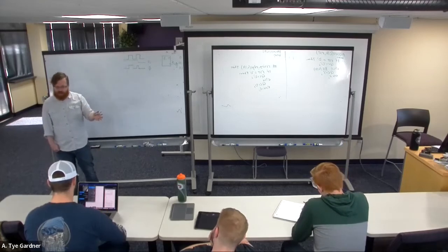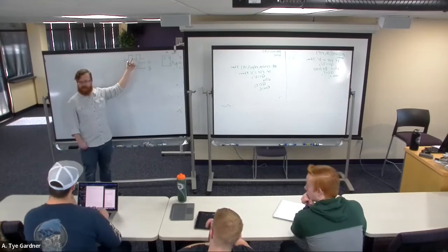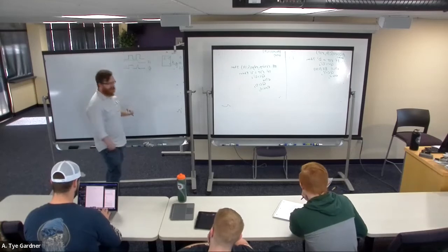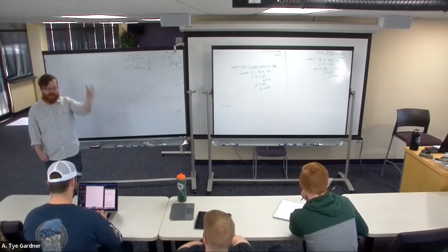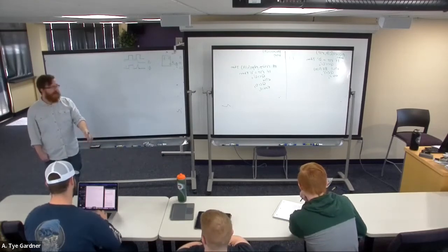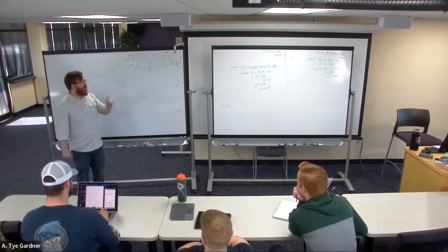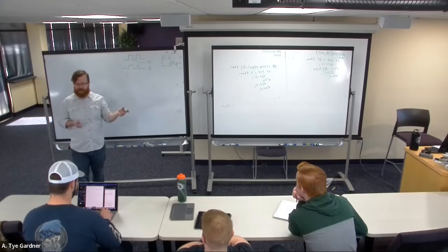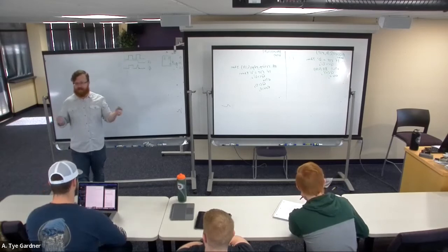The issue gets further exacerbated the closer this gets to the end of this clock, because now it's going to do a little spike up, spike down, right? It's going to try and change to a 1, but it doesn't have enough time, so it's going to fall back to a 0. And now this triangle may or may not register. And if the signal is going to multiple flip-flops that have multiple clock enables, some of them might clock in the new data and some of them might not. And now they're randomly off because each of the devices are different.